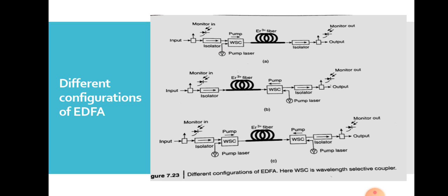Also you can see that there is another tap coupler. Instead of this dichroic coupler, there is also another tap coupler at the input and output sides, which is used for monitoring the input and output.